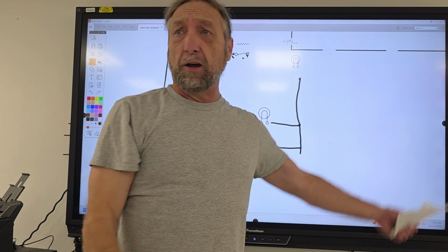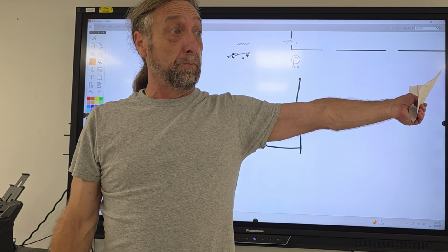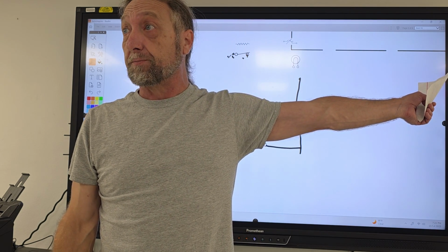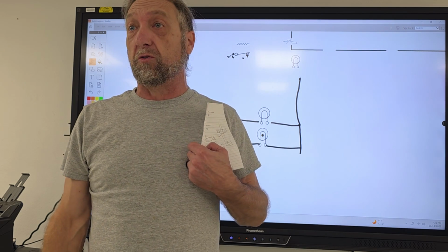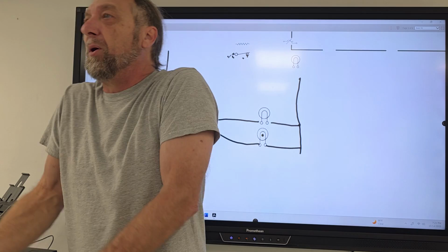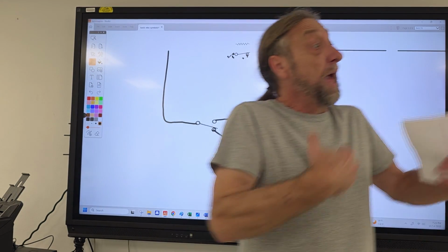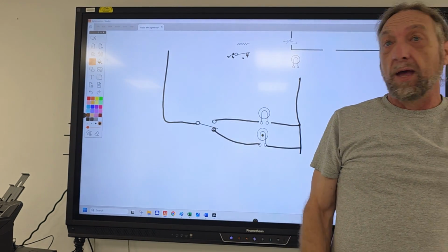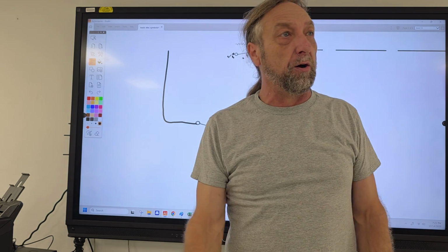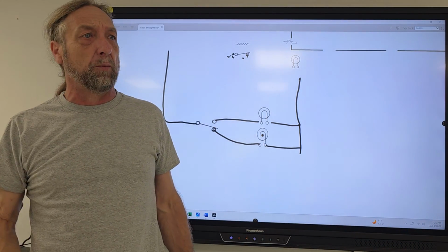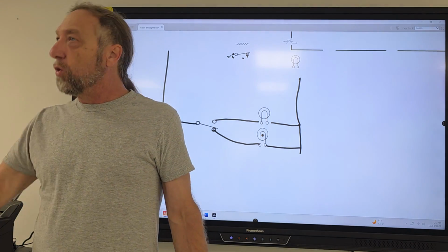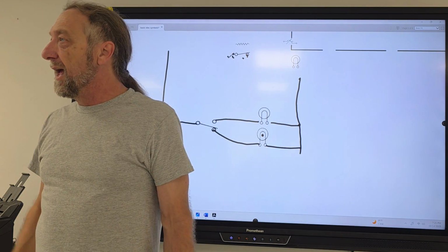But just the other day, you guys were working on a GE dishwasher. There was no diagram in it. Without a diagram, it's even hard for me to troubleshoot something if I don't know what the part is, how that part works, when that part turns on, and how much voltage I get to the part. So reading these diagrams and understanding how they work is how you're going to troubleshoot this appliance.